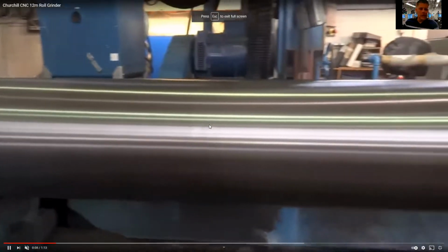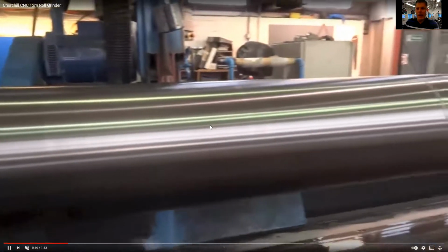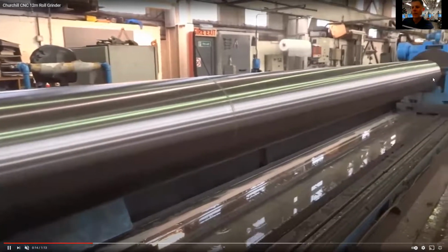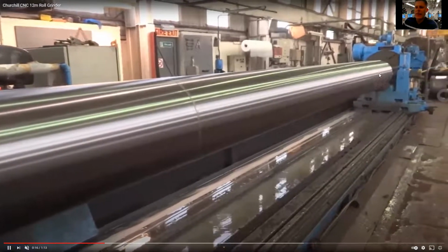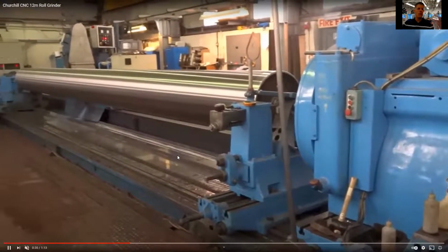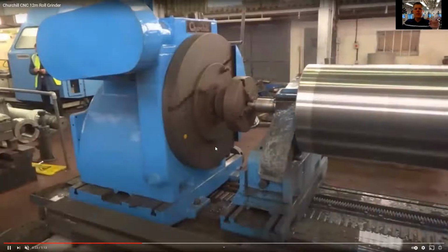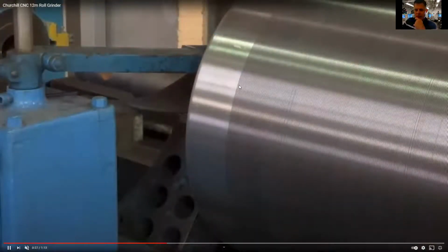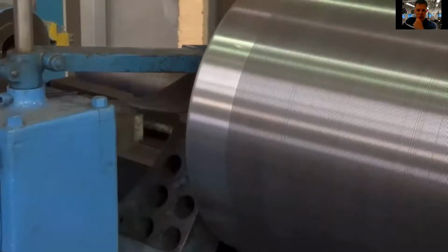surface finish. So now, remember that 36-foot long part we saw at the beginning in 145 back with a lathe? Here it is getting roll ground afterwards. So after they turn it, it's got a helix down the part, right? Because when you do turning, you're creating an inch per revolution value down the part. You can see the surface finish differences right here. So you can see on the right, you have the turn surface finish.